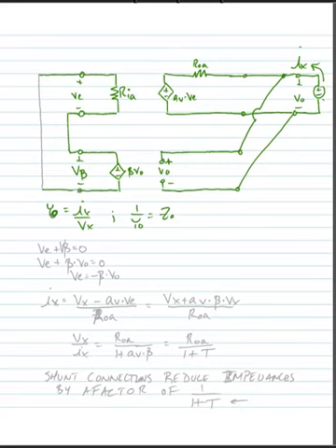Alright, so when we find conductances, we need to make the voltage at the opposite port equal to 0, and so we're going to short circuit the opposite port that we're looking at to find that conductance. And what we would note then is that VE plus V beta is equal to 0, just doing KVL around the input loop. We know that V beta is equal to beta times V out, so we can say that VE is equal to minus beta times V out.